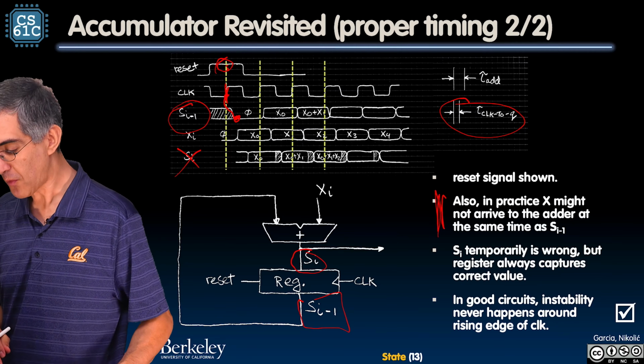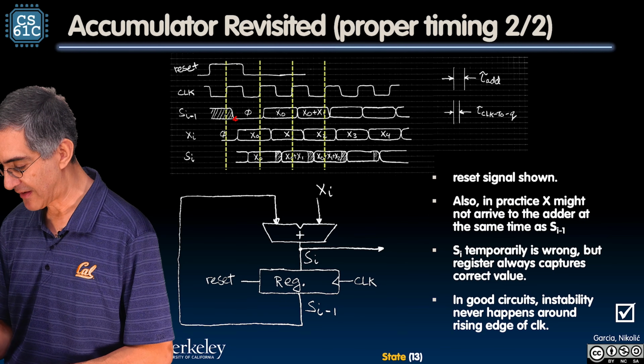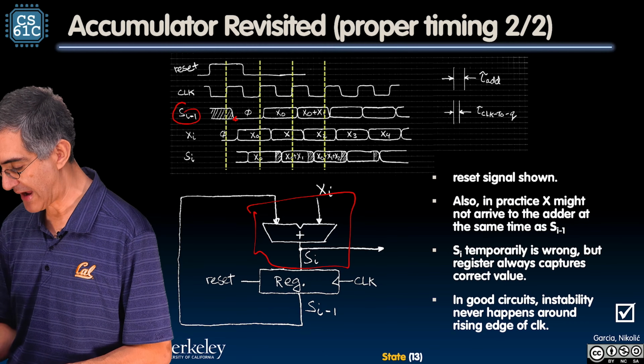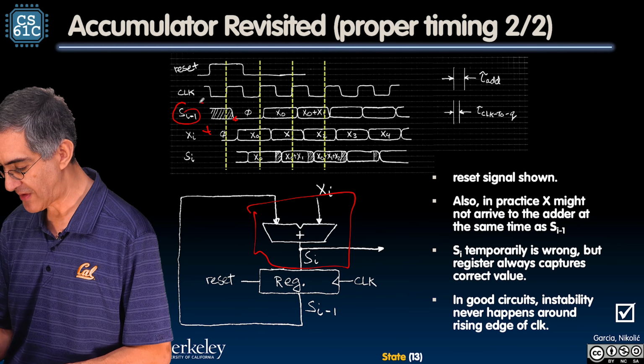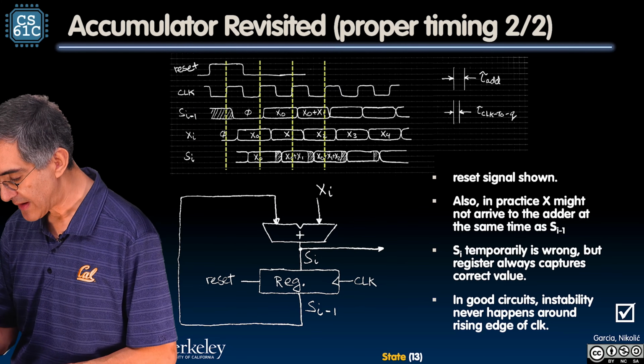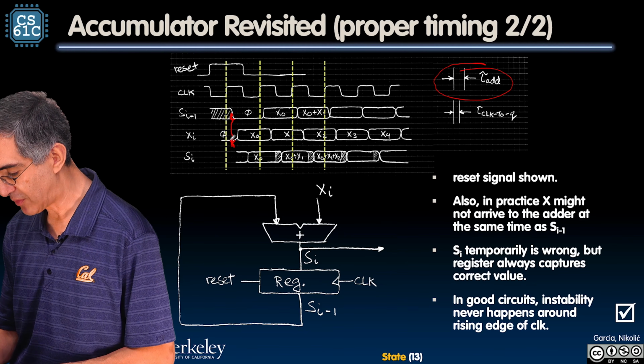So now, what's the next thing to happen? Well, that's a 0. And now X of I, what's the next device? This adder has S of I minus 1 and X of I, and this is the adder, so same place. So both of these control what happens there at the S of I output. So here is my 0. This was a 0 before. So I have to wait T add, and that value after T add is available here. 0, 0, I'm going to write here.